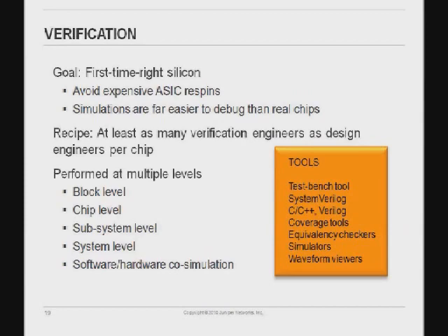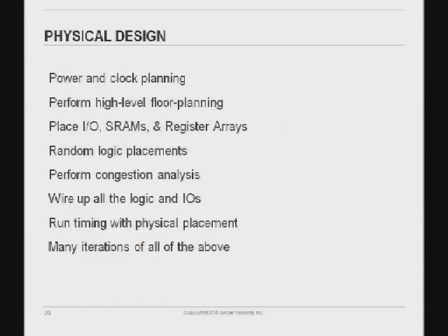And then we use simulators, we use waveforms to look at the waveforms so that we can see what's wrong when something doesn't work. And there's also another aspect of it: after those are synthesized into gates, we need to place them physically on the die. And we just don't do that randomly.